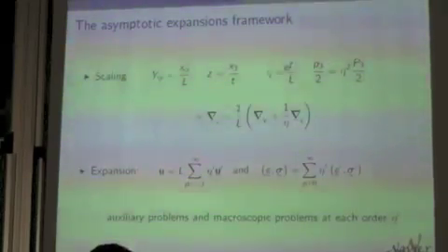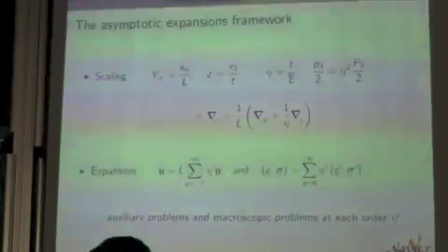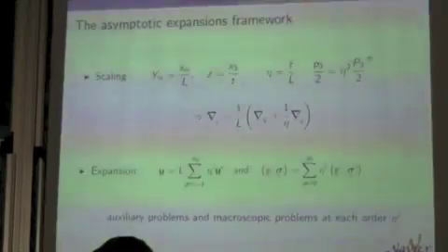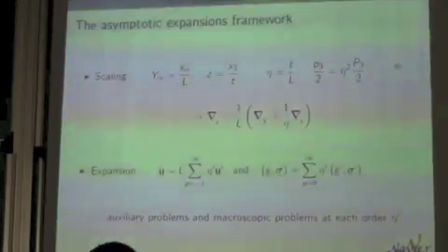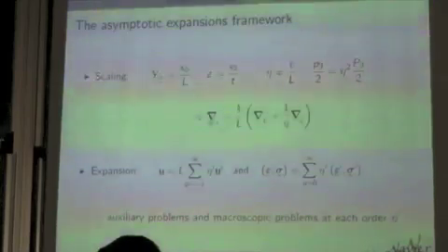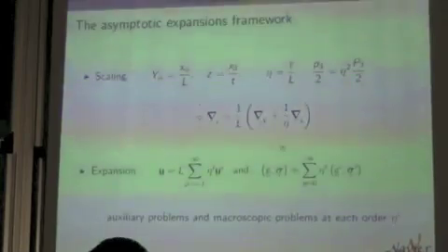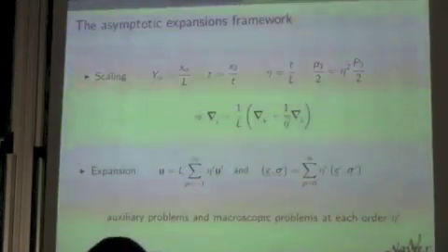So the small parameter is eta, the inverse of the slenderness ratio. You need to scale the out-of-plane loading, but this is just a matter of choice. The main consequence of this choice is that you split the differential operator into two parts, the in-plane part and the out-of-plane part, with different scalings.